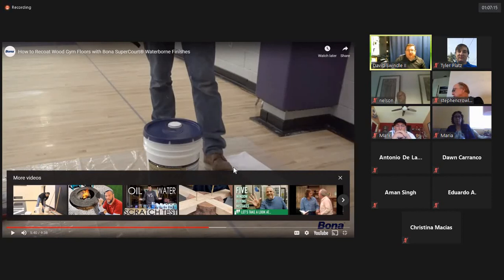I ran into this situation years ago with a community college where the custodian, we were doing a gym that was about 15,000 square feet. He mixed all the pails up. Worked out great until we got to the very end. Because they had been sitting there for hours, that last pail did not properly coat on the floor. It was already starting to cure before we could get it on the floor, so we had a lot of problems with it.